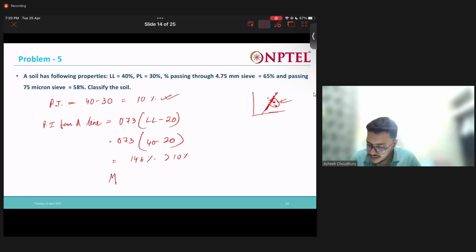Liquid limit is between 35 and 50%, so it will be MI. So it will be MI.